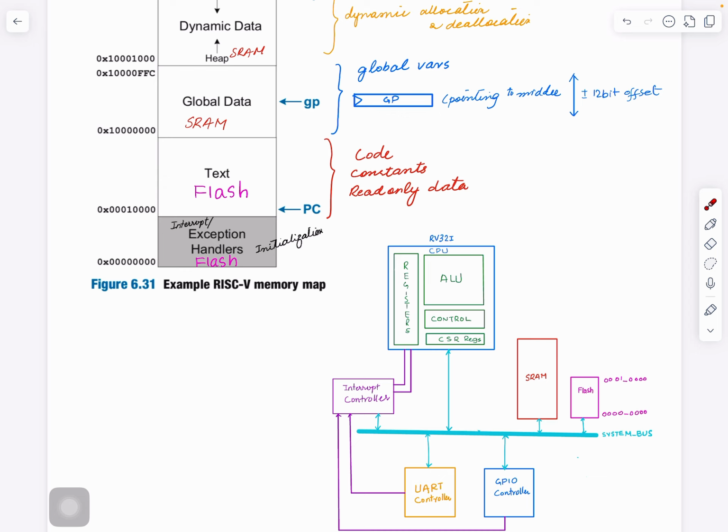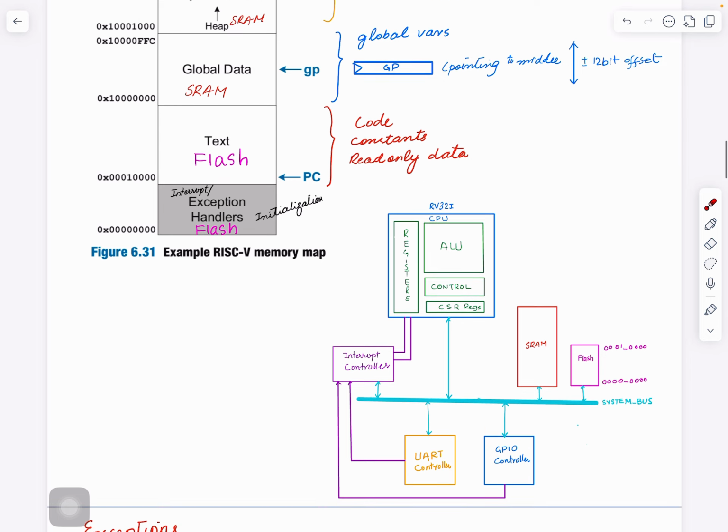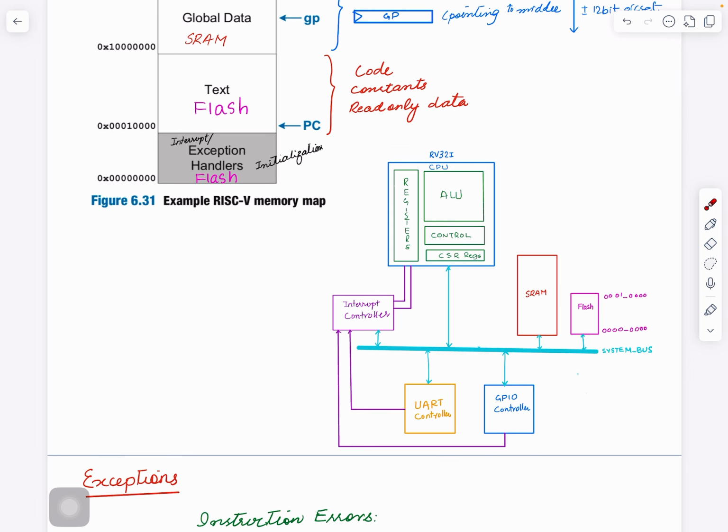So what we will do is, this will have some register that allows the CPU to read that it's ready, or when you want to send something out. Let's say based on the input you figure out a signal went high and you need to process it, and it's a temperature sensor. When temperature reaches a certain point, this needs to turn on a fan or AC.